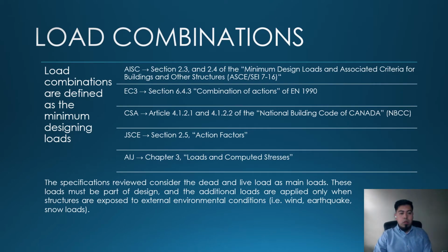Combinations. The load combinations are defined as the minimum design loads. And the main loads are the dead loads and live loads. Additional loads are applied only when structures are exposed to external environmental conditions, like wind, earthquake, or snow. The load combinations can be found in the sections that are shown here.